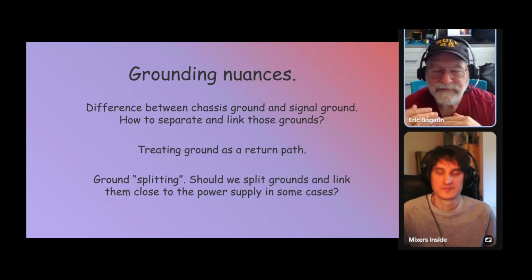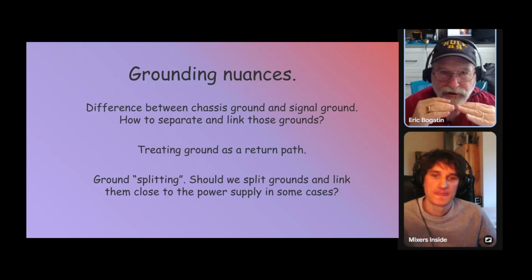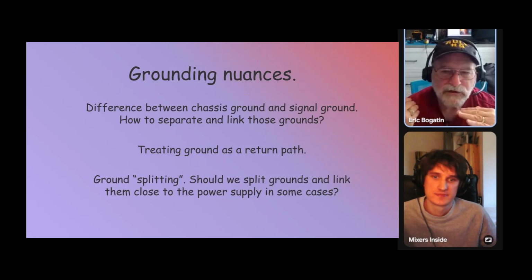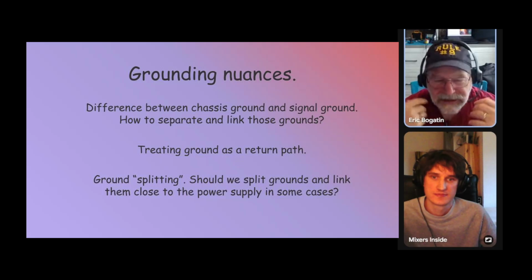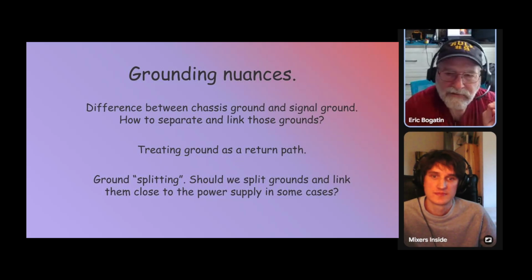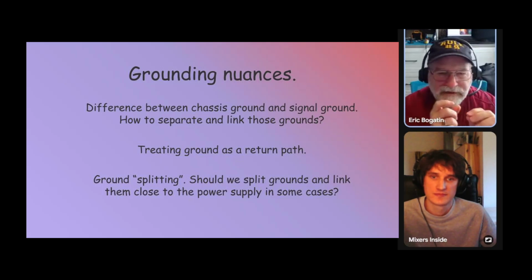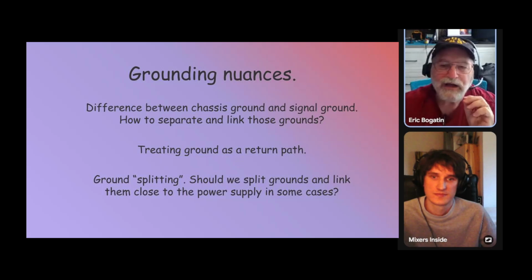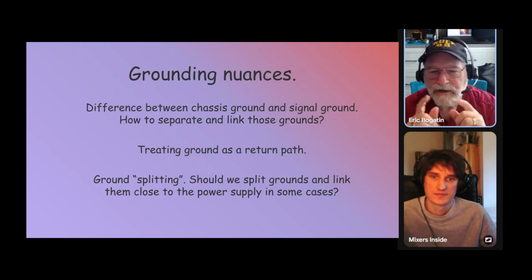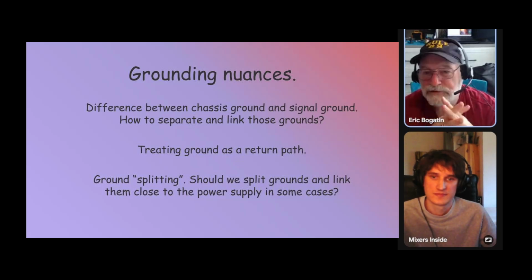And you still have the benefit of a low current carrying line as the reference, with low voltage noise on that line. So it's really about changing your mindset, thinking about your low-level signals as differential signals and carrying that differential signal from the source of the sensor, wherever that microphone is, all the way back to the preamp, so that you have high-level signals on the other side of that preamp, carrying it through a differential pair.